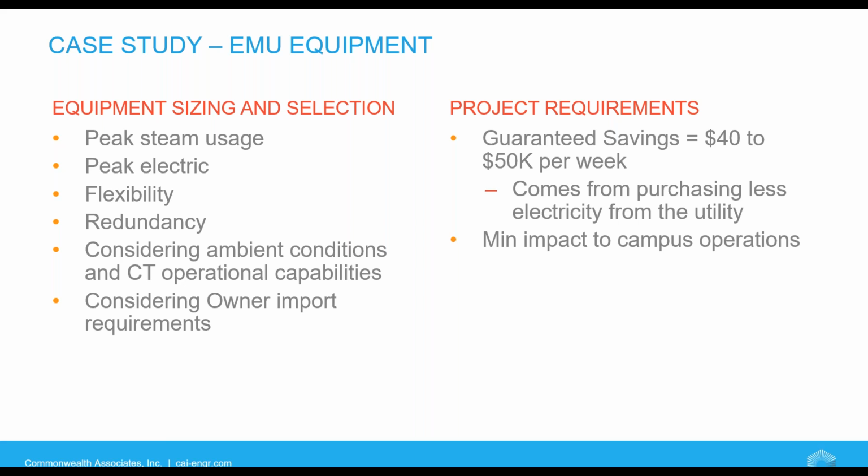If this CTG went down, then they would just pull from the grid. And it was known that steam could be provided from the existing boilers as a backup. With this understanding, they knew they could install a single CTG HRSG train and still have the needed redundancy. A similar evaluation, though, was performed for all the remaining equipment, right down to control valves and circuit breakers.